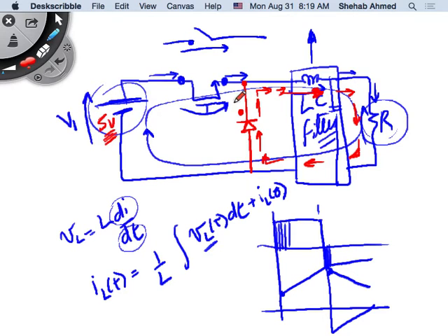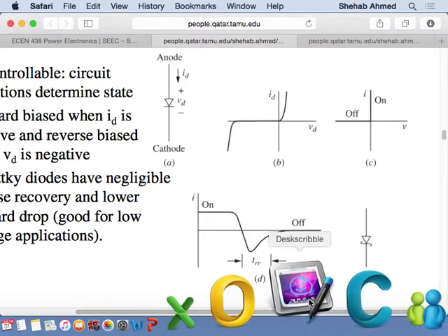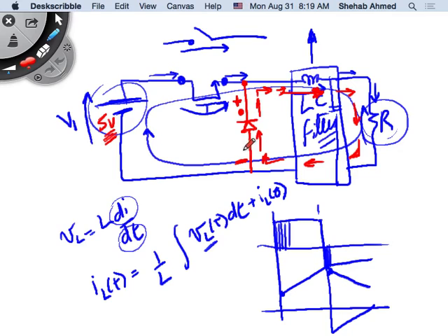So I put the highest positive voltage here, and I've put this negative voltage at this point in the diode. So what will this do? We said that the diode will block if my cathode sees a positive potential and my anode sees a negative potential. So basically VD is negative, right? This point sees a positive voltage and this point sees a negative voltage. So I've put a reverse voltage across the diode and it blocks.